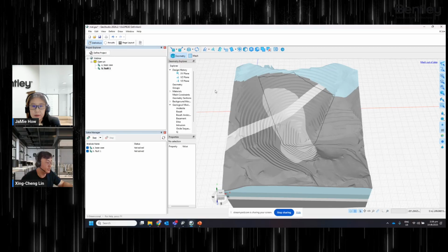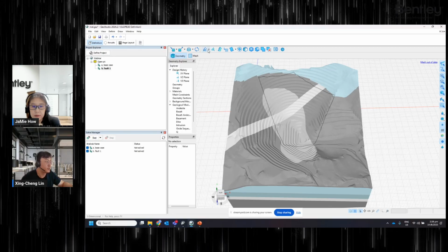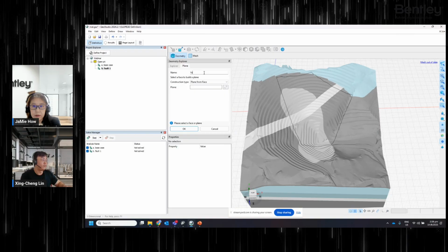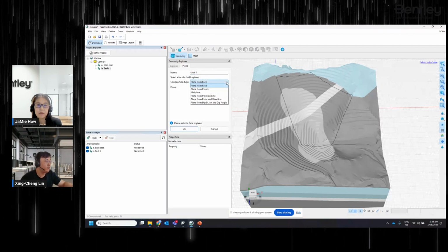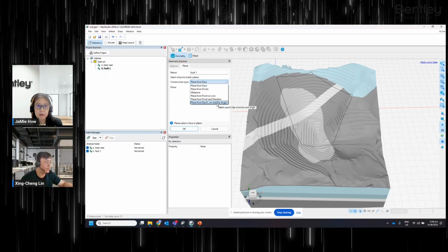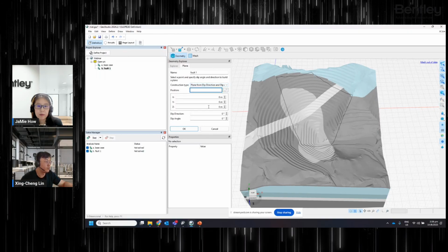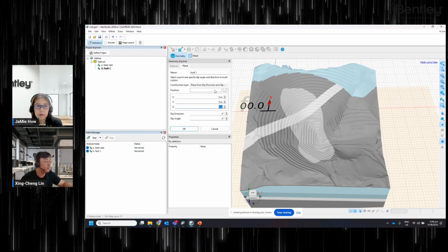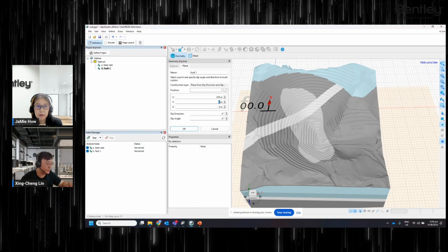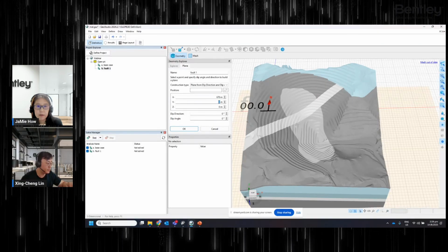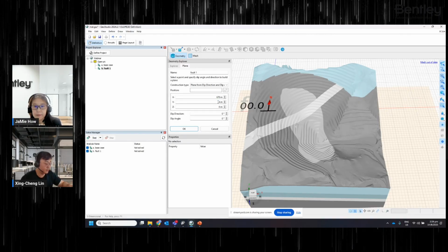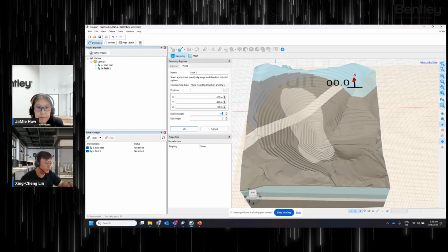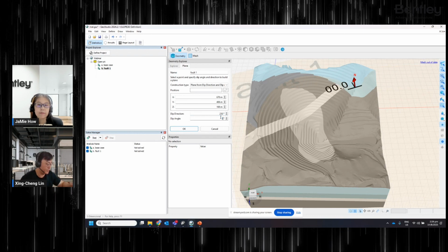In this case, I'll look at the plan button, which is here. Right, I'm going to rename it. This will be fault 1. And for construction type, we're open to various options. In this case, we go for the plan from dip direction and dip angle. Then the XYZ coordinates as the reference point. All right, and dip direction will be 250, dip angle 30.